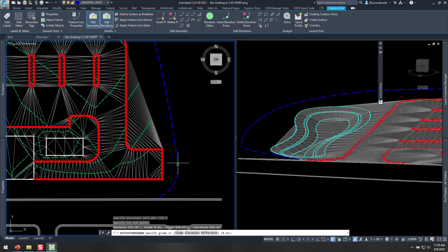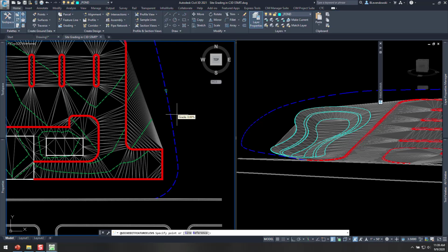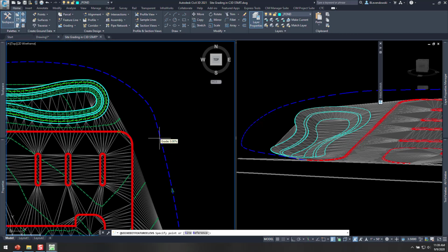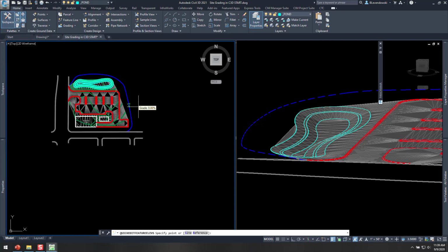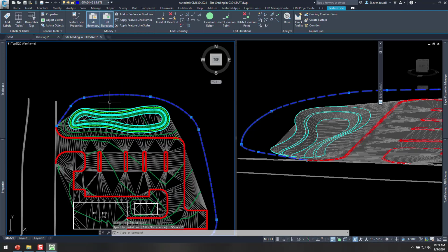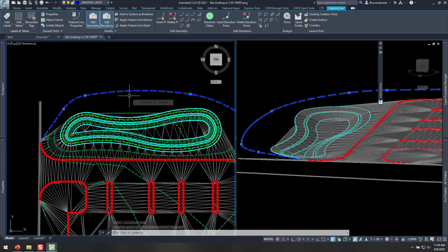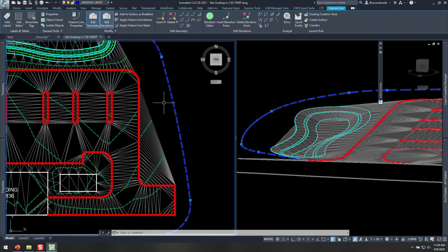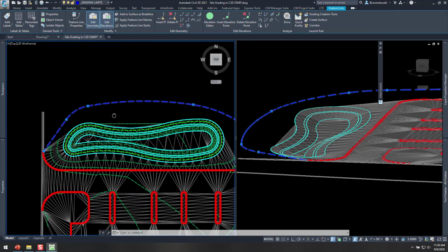It's prompting for set grade. The current grade is at 0.16. Let's flatten that to 0. The whole top of our berm will be at a 0 grade. And in that way, what I end up with are flat grades all the way along the top of this. If I use this quick elevation editor, you can hover, and you see I've got 0% there. Now one strategy, if you're not doing a berm, is you could grab elevations from existing and throw it into your surface, and it would give you a flexible daylighting or grading limits edge.